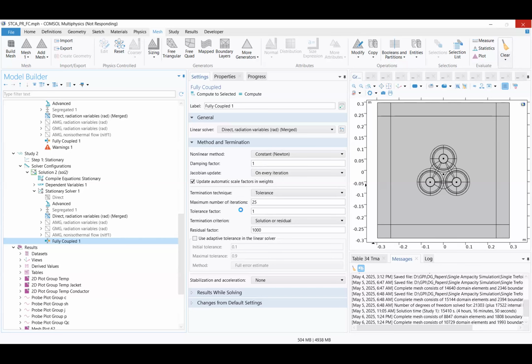For a time-dependent solver, I think that if you need to use a damping factor that is too small, then something is wrong with the model. I think you're better off reevaluating the model, reevaluating boundary conditions and stuff like that, if that's the case.